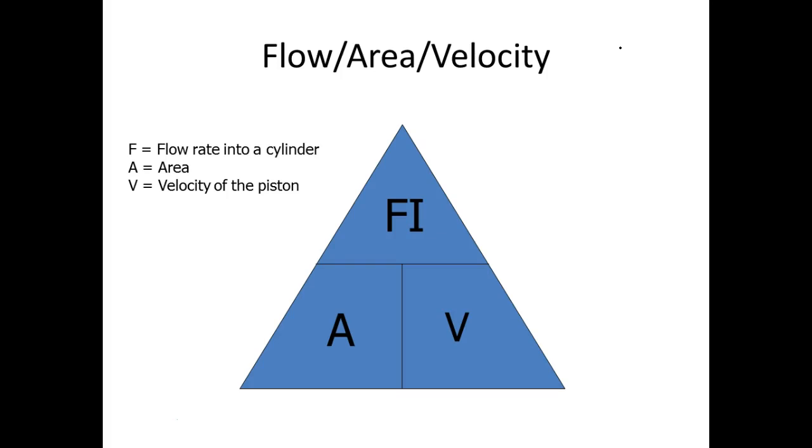We have these valves we'll look at called flow control valves. What do flow control valves do? They don't change the force. They change how fast it moves. If I can change how fast it moves, then not only can I get the same force, but I can also now set the speed. So that's one of the valves we have available, called a flow control valve, and we'll see those over there. Are we okay?